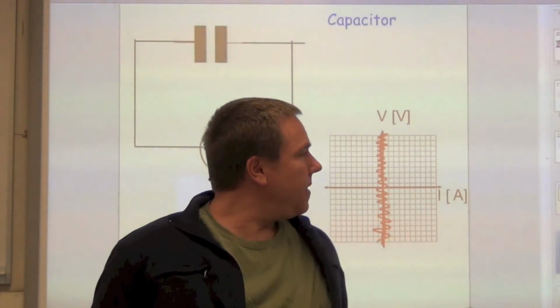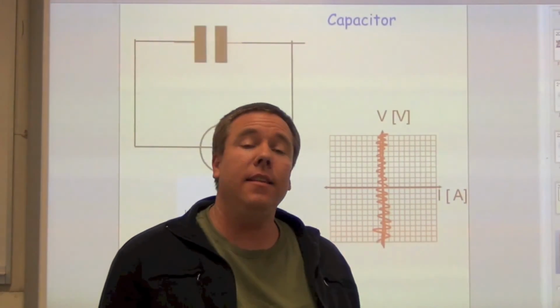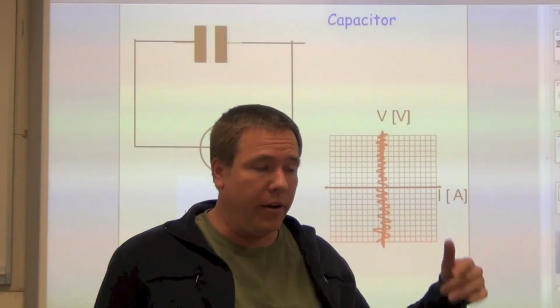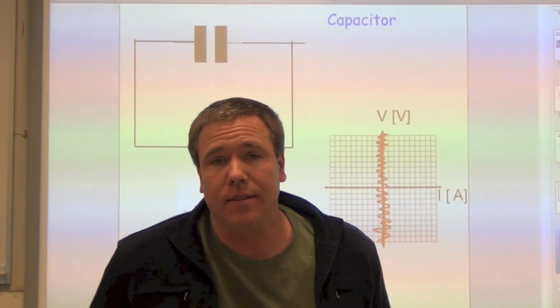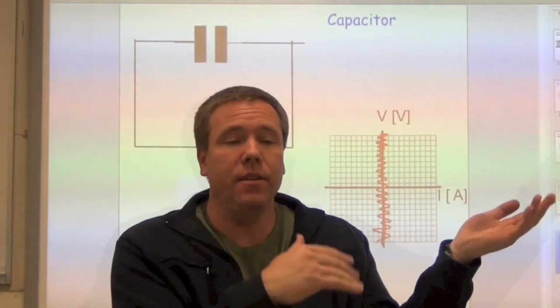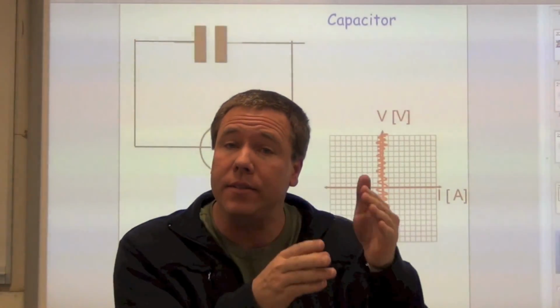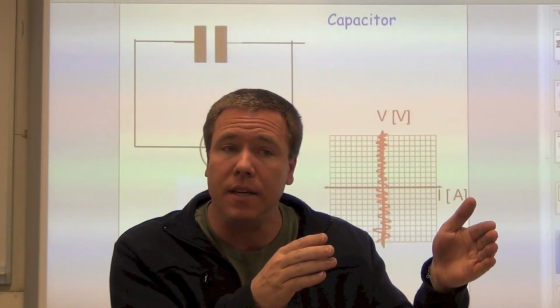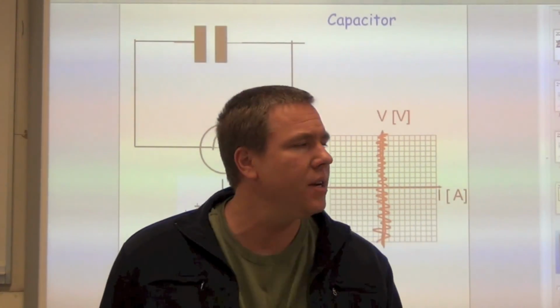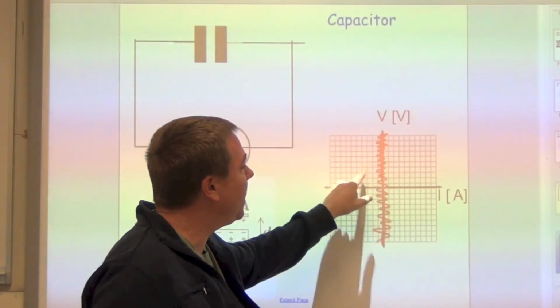Okay, and that's not to make you think that, oh, we're suddenly activating Ohm's law for the capacitor. No, this wiggle in the current is simply a factor of the uncertainty in the measurement. The interface cannot know the current exactly. It's plus or minus so much because of the uncertainty. It's in the milliamp range. And so if you zoom in, you'll see some data that's wiggling.